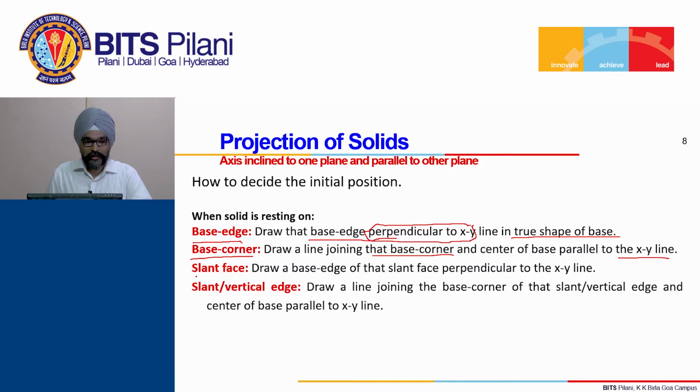Similarly, if it is resting on the slant face, we have to ensure that the base edge which is contained in that slant face, on which the solid is ultimately resting, is perpendicular to the xy line.